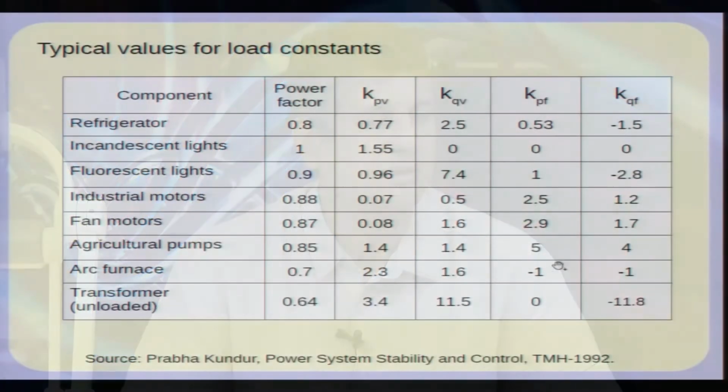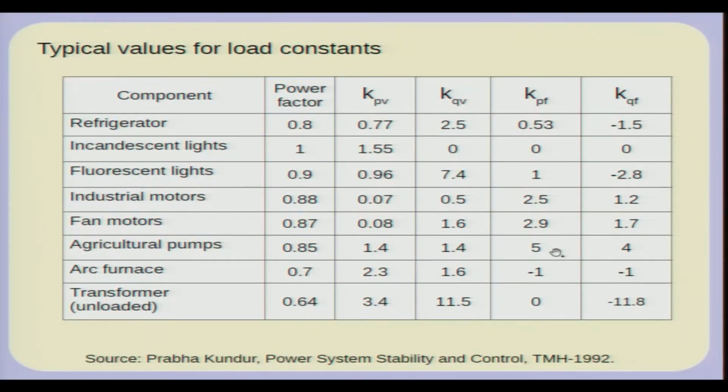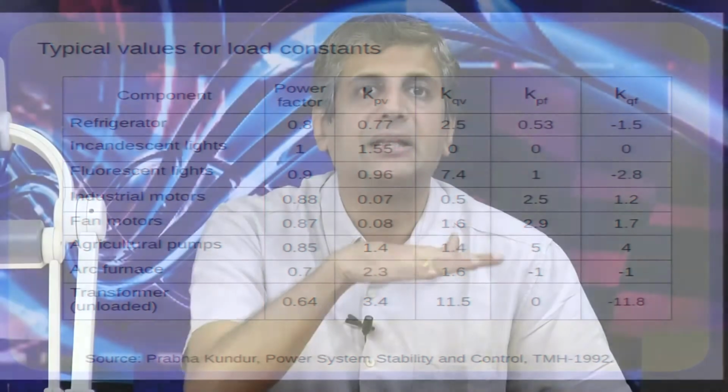So, having a positive coefficient KPF is useful because it contributes towards coming to an equilibrium as far as frequency is concerned. If frequency increases, the power drawn also increases, and that ensures that the rotating mechanical system comes to an equilibrium. So, both the governing system as well as the load frequency dependence are two factors which ensure that frequency reaches an equilibrium.